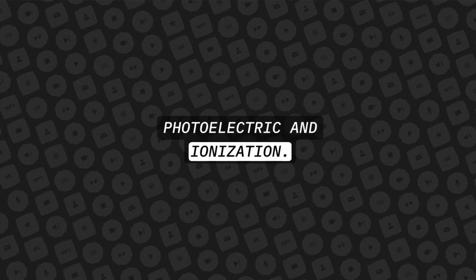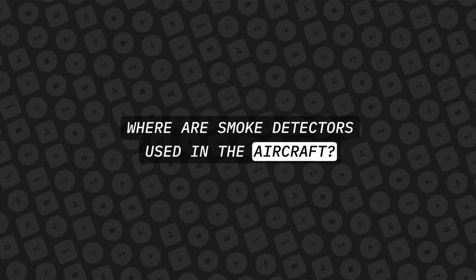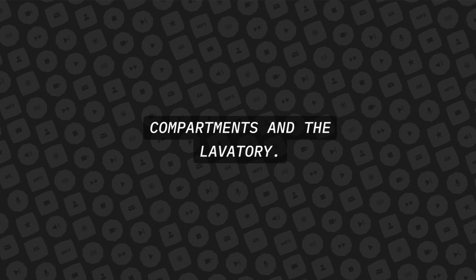Photoelectric and ionization. Where are smoke detectors used in the aircraft? They are commonly used in cargo and baggage compartments and the lavatory.